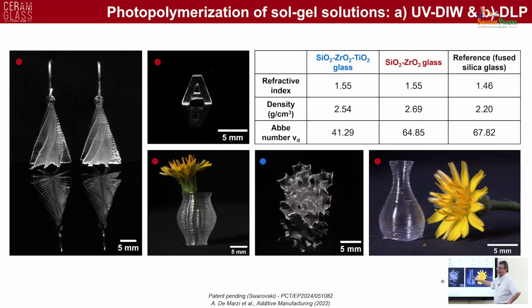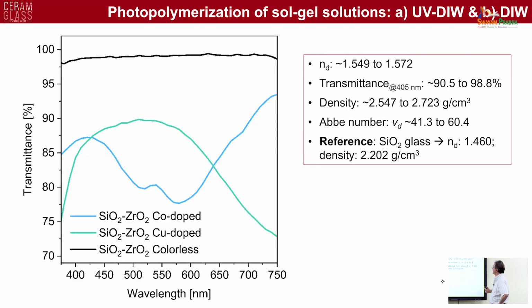And of course, you need high refractive index because you know that the reflectance from the surface of a glass is related to the value of the refractive index. So the higher the refractive index, the higher the amount of reflected light, so the glass is more sparkling. And if you work with jewelry, you want sparkles. So that is why we developed this.